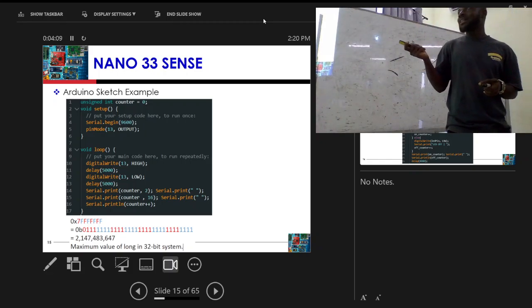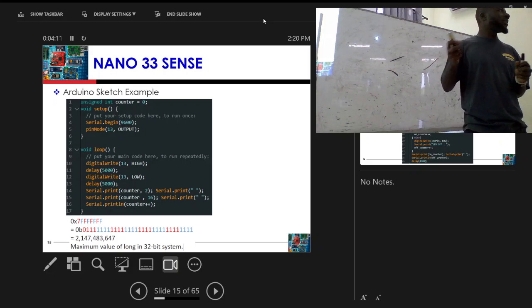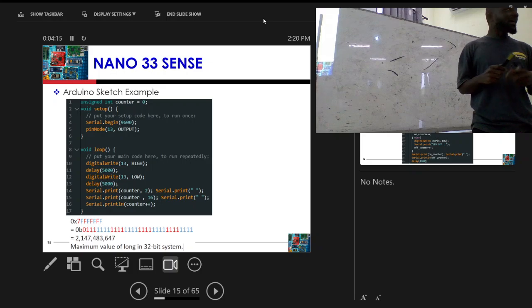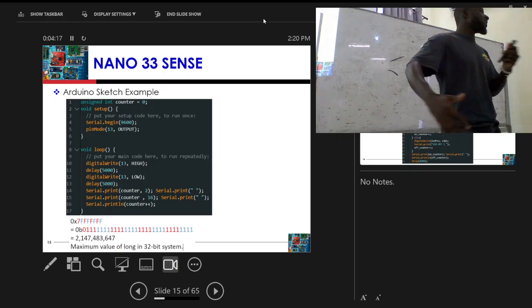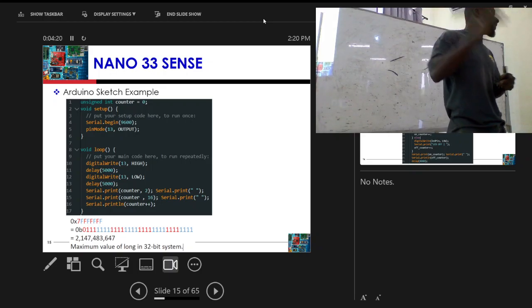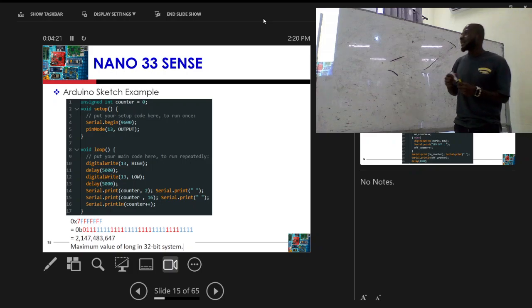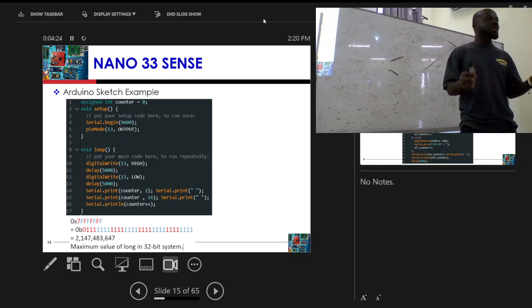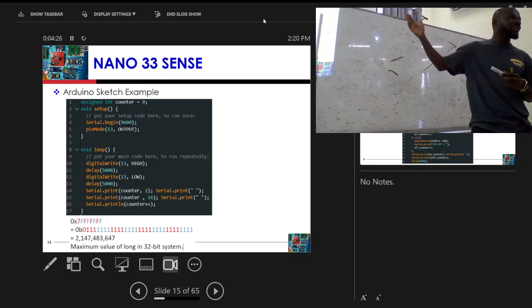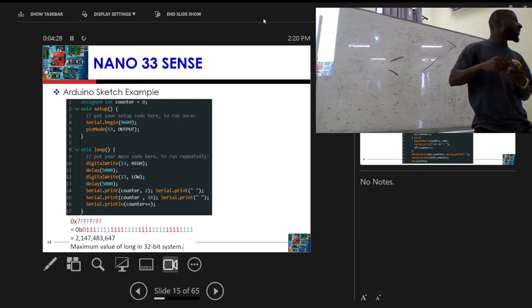Right. So it means that this first line of code will establish some kind of a way to talk to the Arduino board from the PC, right? How to send data to it. And I explained the last time that Arduino is all about libraries, right? If you see Serial.begin, Serial is a library, begin is a function within the Serial library, right?